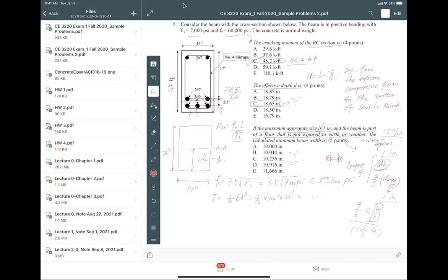And now we have number 4 stirrups. So make sure that is okay to use table A5. Okay. My suggestion is you don't use table A5. Always do hand calculations. Okay. And the reason for that is I made the problem. So I know you cannot use table A5. Okay. So I hope you're happy for this tip. Free tip. So always calculate beam width.